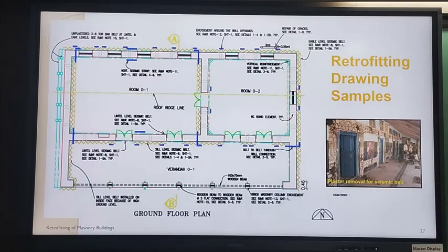Right, now this is a typical plan that is to be drawn, and the plan shows all the elements which are to be added. You can use any kind of notations, and you need a legend for that. But like this wavy line is a belt, seismic belt. This blue is the encasement around the opening. Right, there is a window here. So there is encasement on both sides, encasement here.